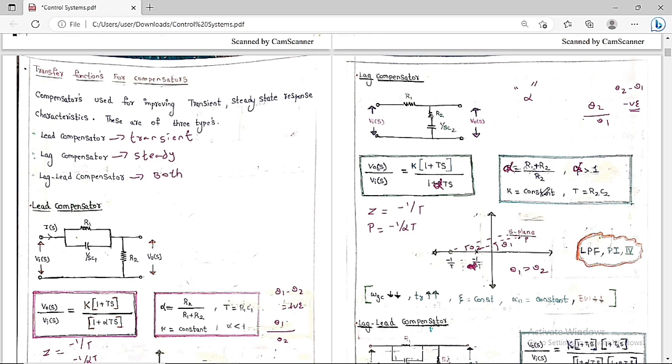This is also called a low pass filter because now the pole is going to come earlier. The pole means simply minus 20 dB per decade. So minus 20 is fixed. Then the zero is going to come, which is plus 20. Already there is a minus 20, so minus 20 plus 20 is nothing but 0 dB. So like this you are going to get.